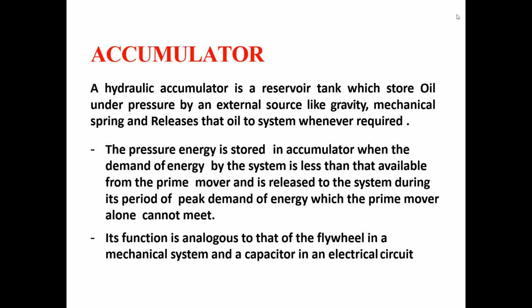Its function is analogous to the flywheel in a mechanical system and the capacitor in an electrical system. You know what a flywheel is? A flywheel is a device which is used to store energy. Same here, the accumulator is a device in a hydraulic system which is used to store energy in the form of high pressure oil.